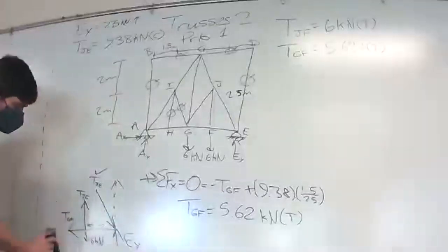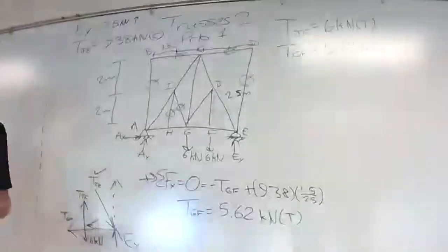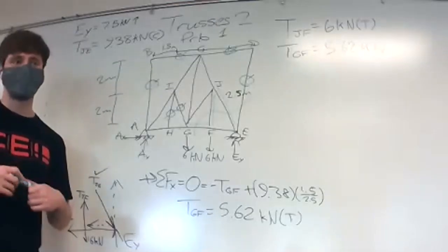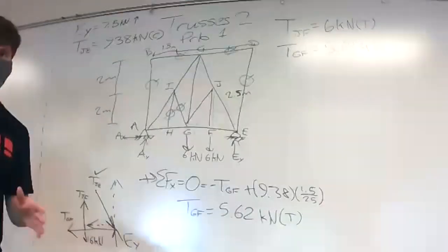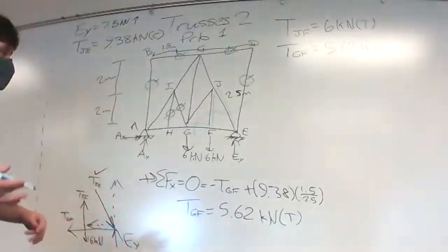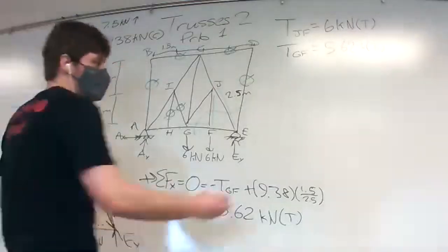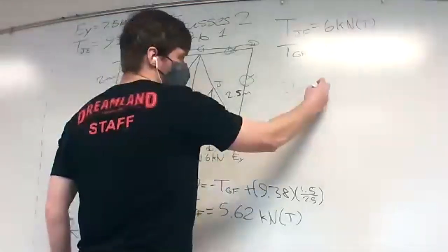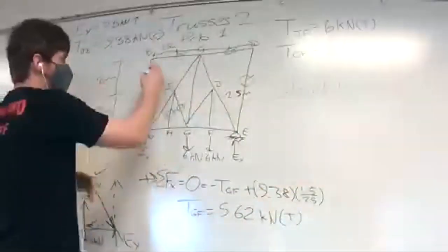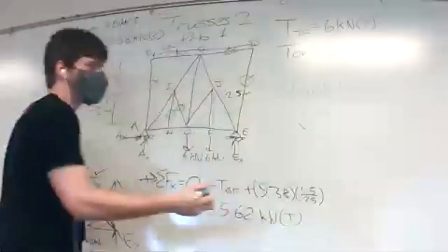So when you have a zero force member, what that means is that the member has a joint where you can set up an equation to prove that it's equal to 0. That's how you can know for sure. But the shorthand way of writing that is, I'll start off with joint B. We model this joint, so we take a cut like that.